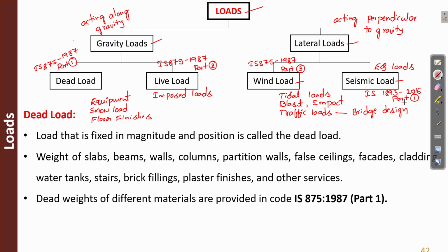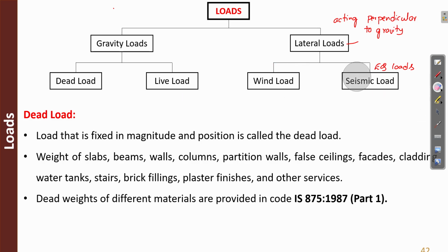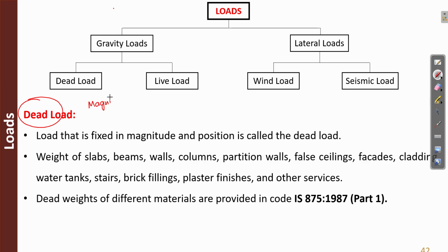First we will discuss the dead loads. Dead loads are constant and do not change with respect to time, which means the magnitude and load application are constant.